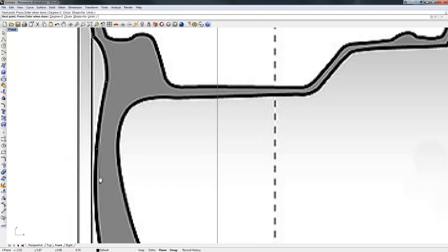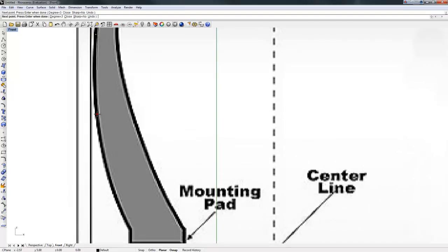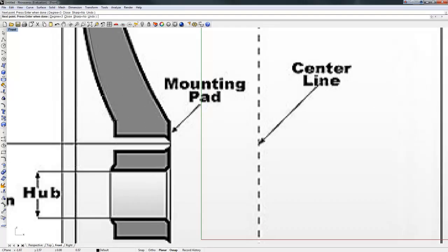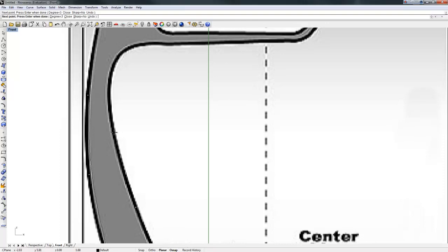Now in the larger curved sections of this, you can go wider spaces between points, but when it gets into sharp corners, you want to add more points in those areas, and this brings those corners in together and makes those corners a little sharper. So just as a rule of thumb, whenever you're creating these control points,